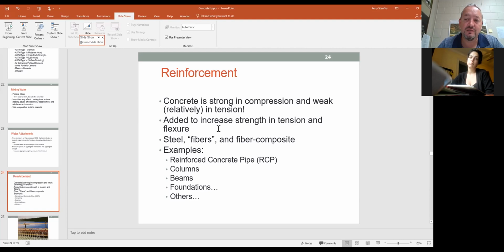When the concrete goes in tension, the strength of all these fibers, there's, let's say, thousands of them in there, will help to resist that. There are also fiber composite rebar, and so sometimes you'll see this as green. Now, they also make coatings for rebar, and I could show you all that if I can remember next week in class. That's for corrosion resistance, but this is actually a non-steel product, so it's a true fiber composite